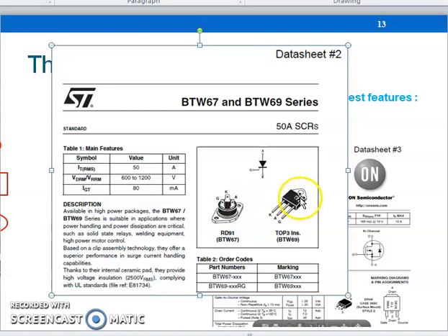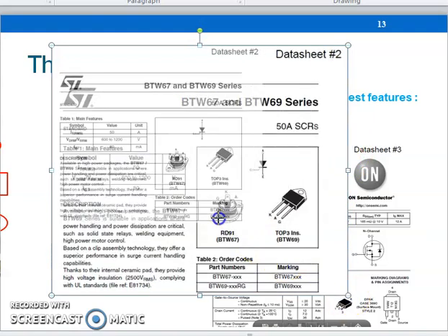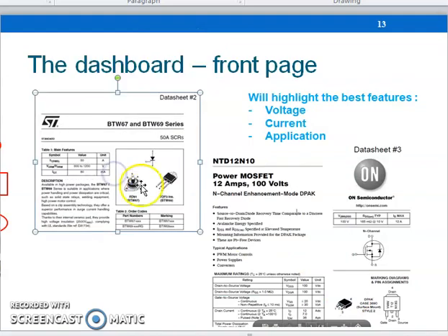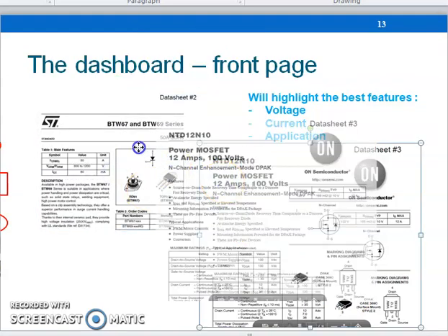This one is the through hole type, meaning that we have 3 legs here. The purpose of the legs is to insert into the PCB board. Meanwhile, the metal tab behind is to be attached to the external heatsink. So it means that this device needs a heatsink to operate. You can operate without a heatsink, but the capability of 50 ampere stated at the front page cannot be achieved.